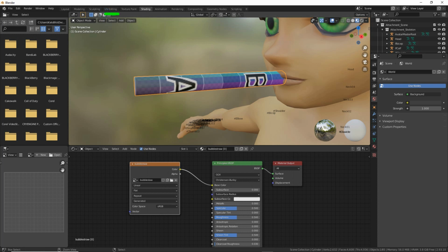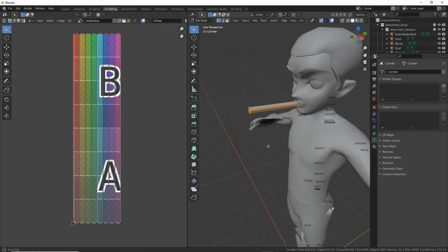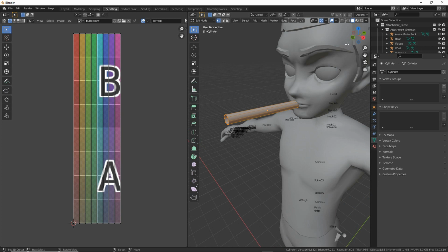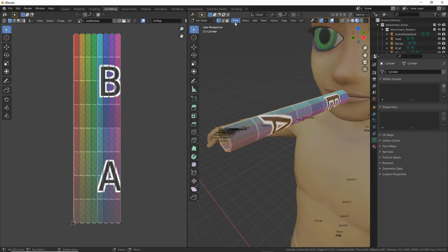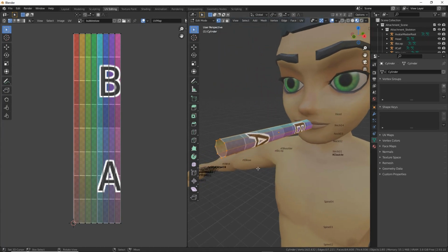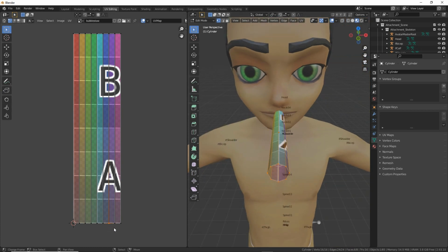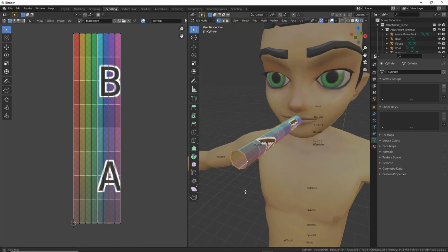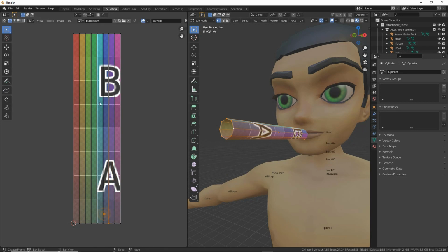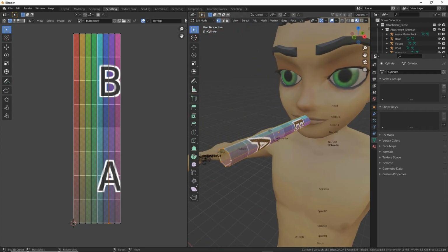So next, UV editing. So let's go into the UV editing workspace, take a look at the UV map. And as suspected, we don't need to do anything with this. Let's switch to preview mode so we can see the image. The UV map that was initially generated fits our requirements because this is a very simple object, but we might have needed to unwrap and edit the UVs. There are a number of ways of doing that depending on what we're unwrapping, but this is good for our intentions and purposes. So that is UV unwrapped and UV mapped. So back to layout.